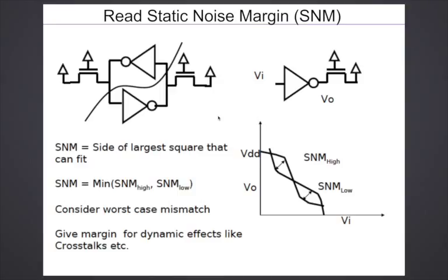So you can get this noise margin number across different conditions, different designs, or for the same design, different voltages, or for the same voltage, across different values of the threshold voltages sampled from the distribution, doing a Monte Carlo analysis, so you get a spread in the noise margin numbers.